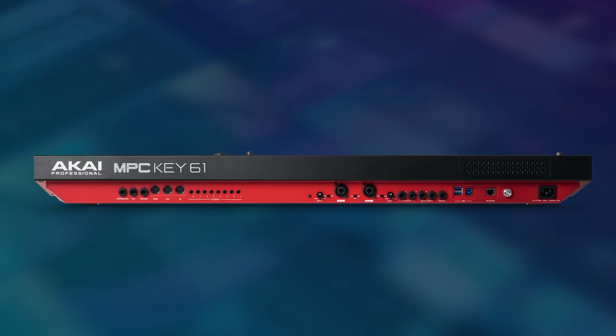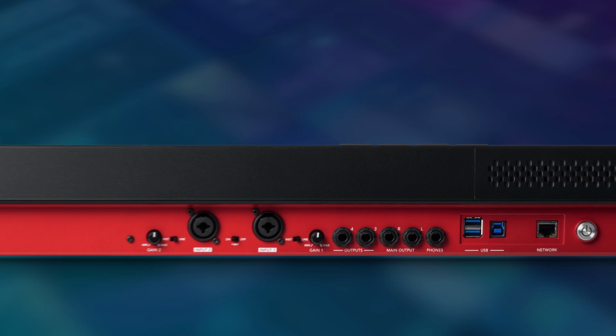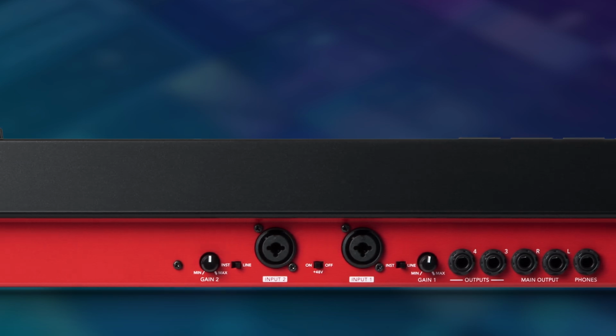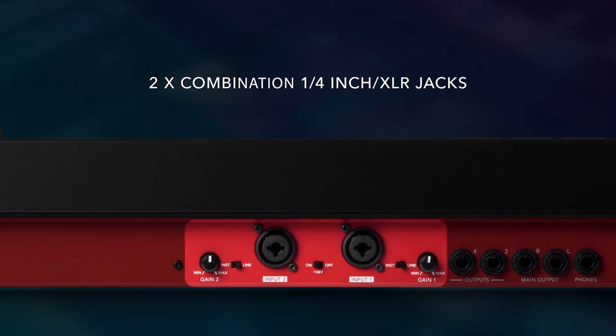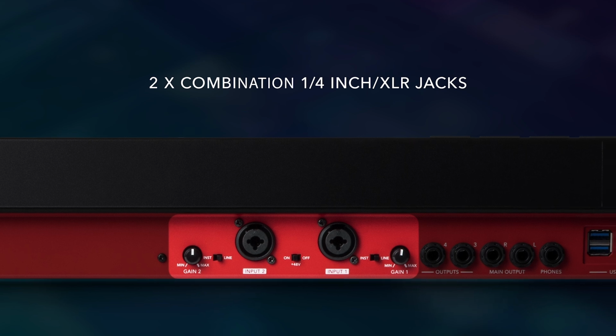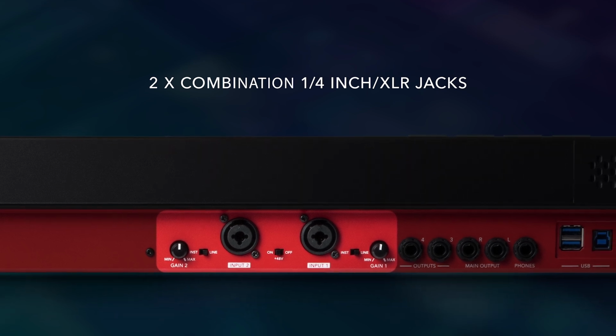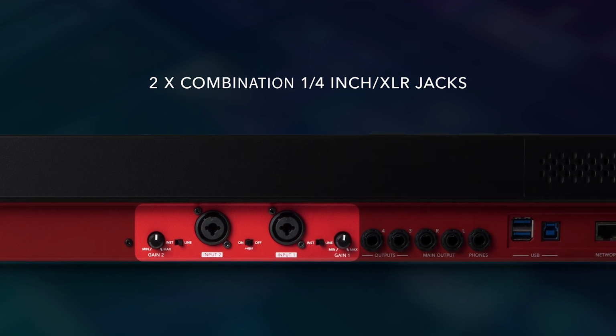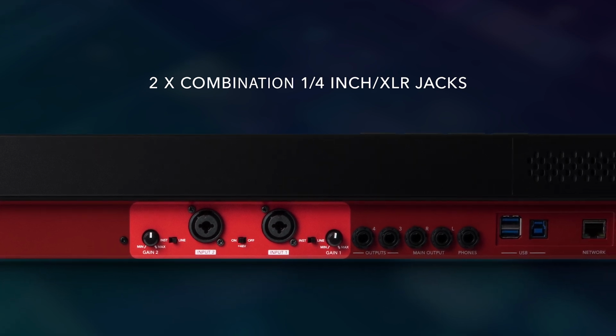On the back panel, we have 4 mono 1/4-inch outputs and a stereo 1/4-inch headphone out. Then we have 2 combination 1/4-inch XLR jacks to accommodate line, instrument, and microphone level sources. Each input has an independent switch to set line or instrument signal, as well as independent gain knobs to set level. Flip the plus 48-volt on-off switch to send phantom power to both input channels.